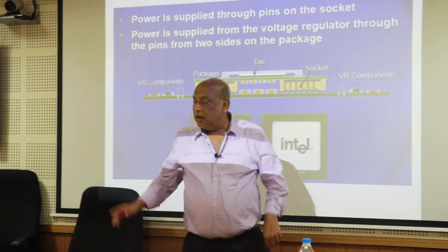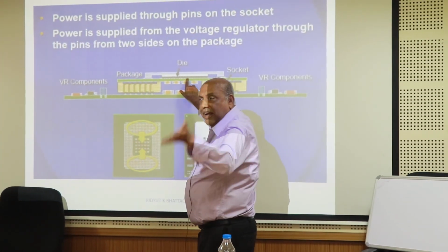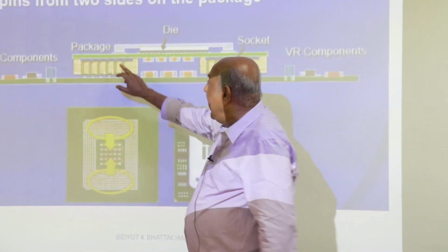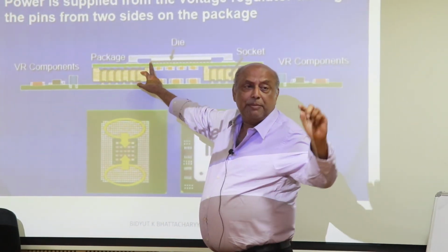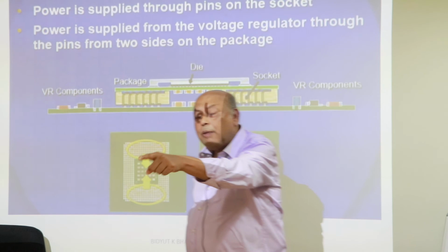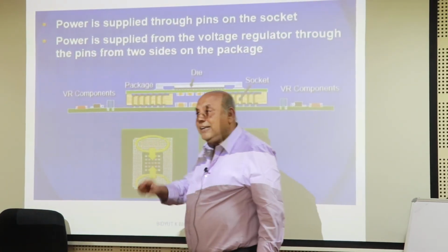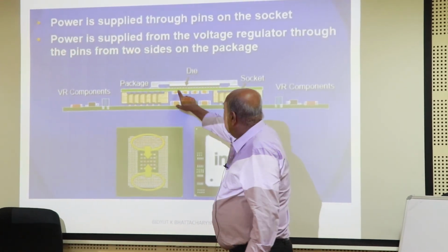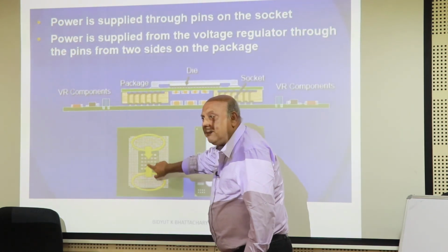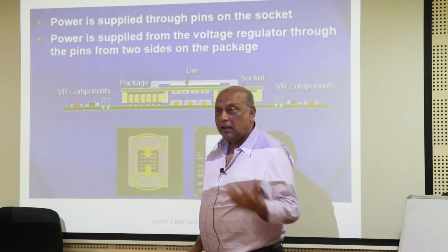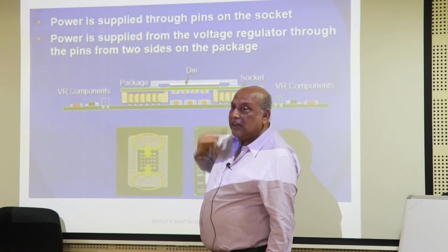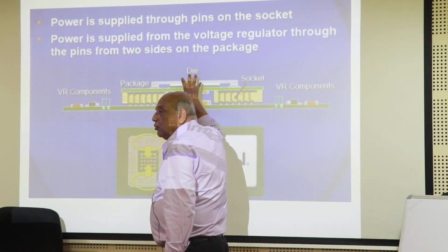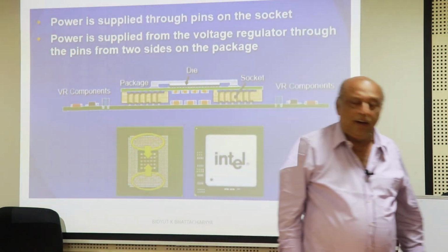So these bumps, like your hair cut half, this pitch, and they're soldered. So there are so many bumps, this height is about 60 micron. 60 micron. You cut your hair how many times? 10 times. That height is this height. Or maybe whatever, 5 times, whatever you cut. They connected, and these capacitors are these ones. Remember I told you? So they supply the power immediately instead of coming from outside. And these are all complex technology to deliver the power to this guy. So you can see 1.6 picohenry number.